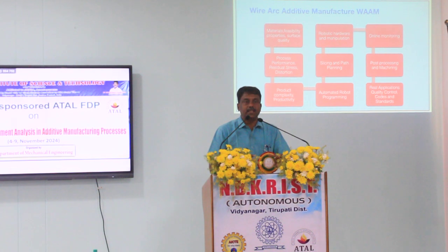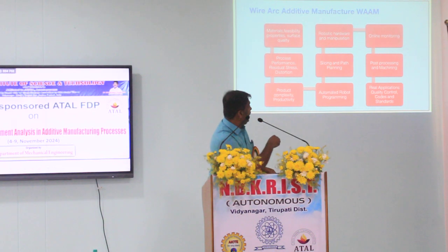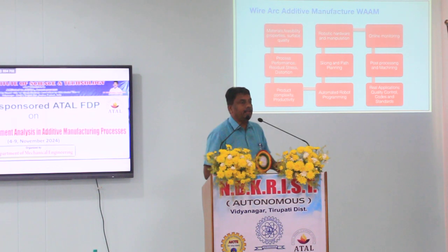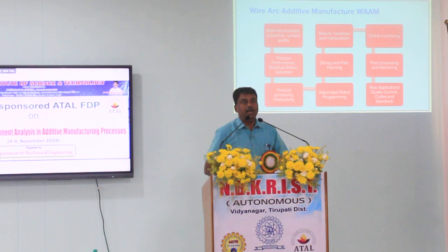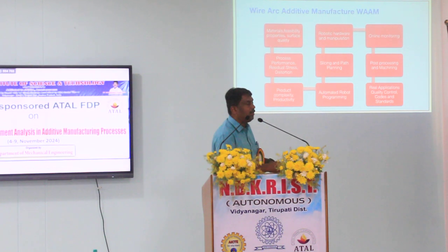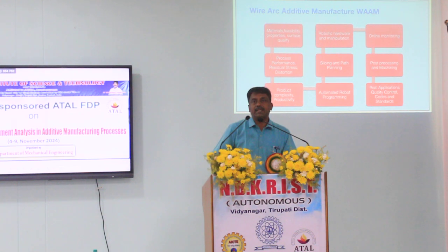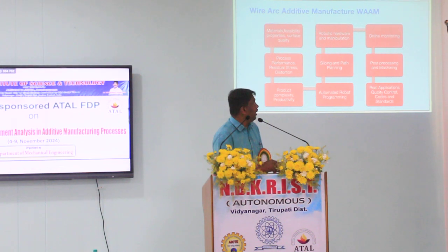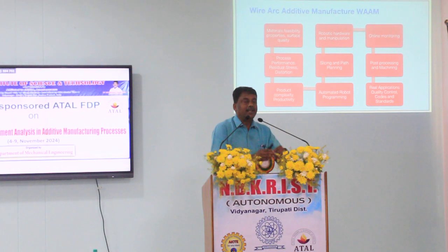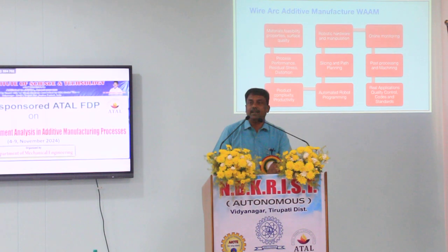Okay, because when a weld pool solidifies, the temperature gradients under the solidifying molten pool are going to dictate how the microstructure evolves. Therefore we carry out extensive FEM simulation, which is an inherent part of it. Both the feasibility study and the FEM analysis give us knowledge about how complex the process is and what design complexities we can involve. Once we have that, we convince ourselves that this part can be printed.